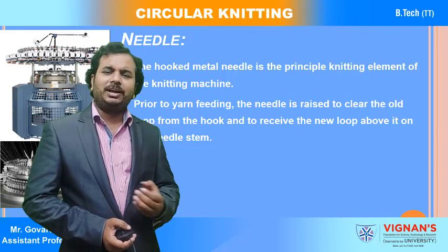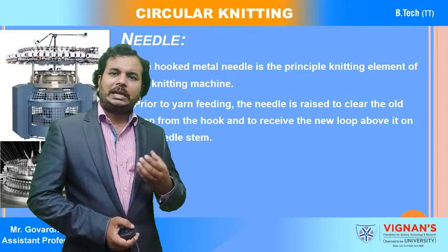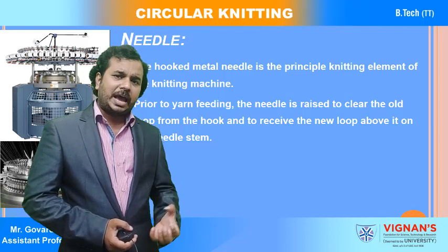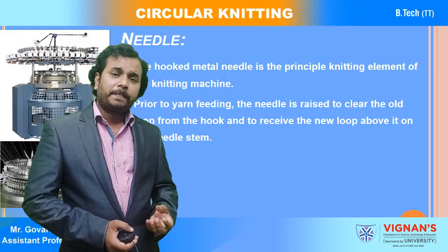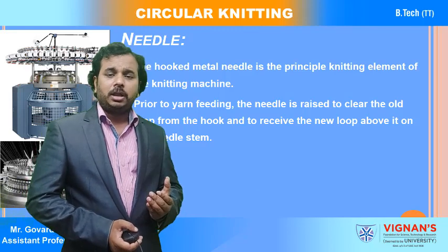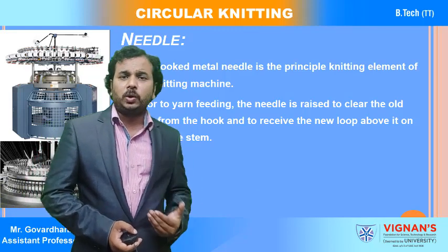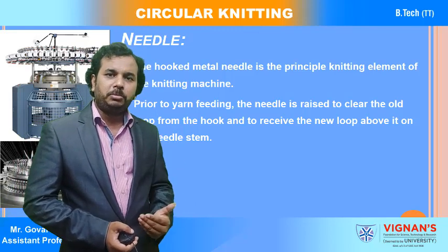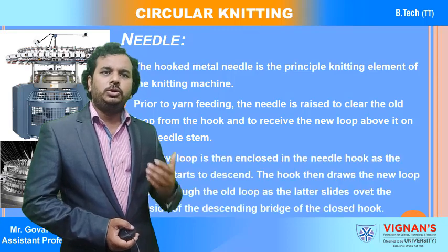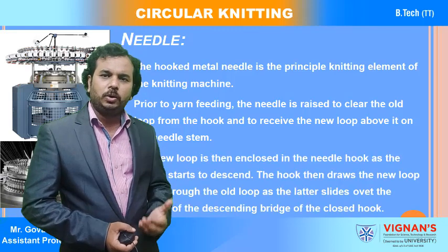So this is how we are clearing the old loop from the latch and the stem of the needle, and how we are feeding the yarn, and after feeding, knocking over, so that through the old loop the new loop is going to be formed. Okay, so the new loop is then enclosed in the needle hook.